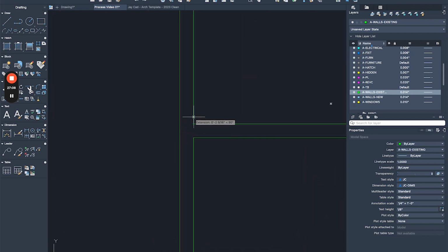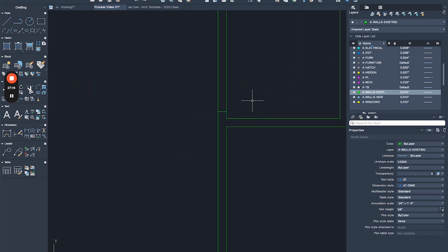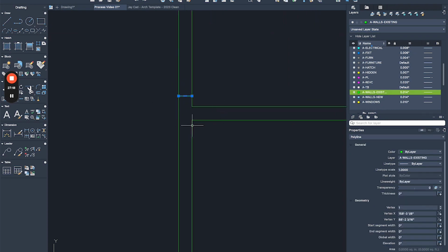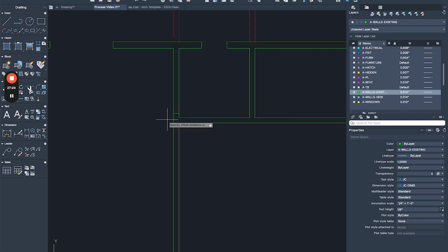All right, so now for interior doors, I like to do 4 inches away from the corner. You can do 3 inches if you want. I think 3 inches is clean. And then I'm gonna mirror this to the opposite side. Actually, no need, I'll just do a polyline. Again, remember, there's literally a million ways to do things.